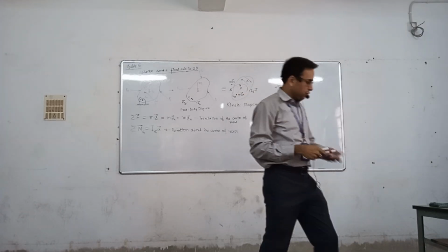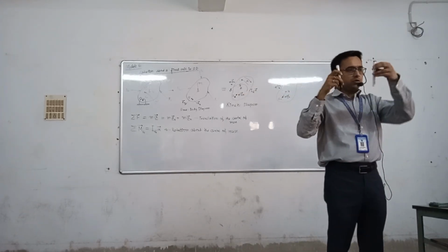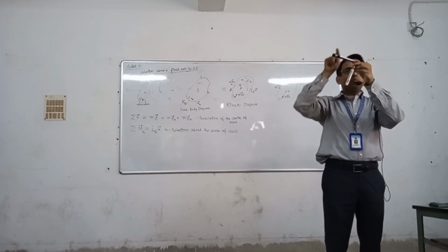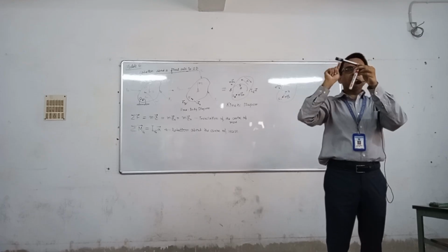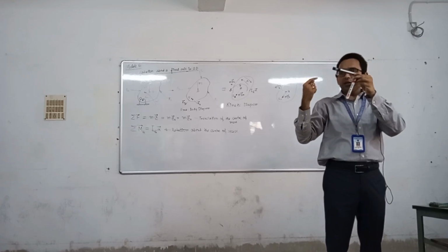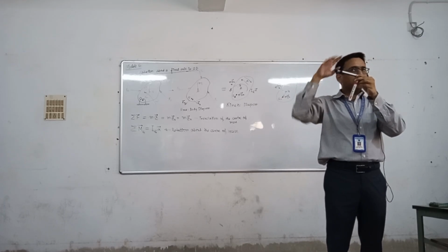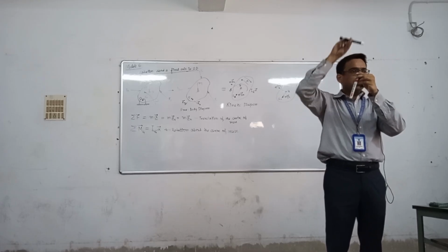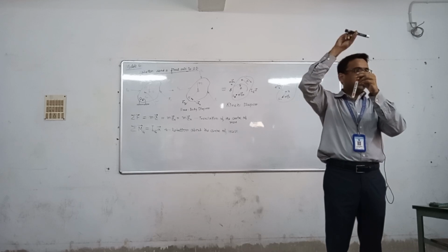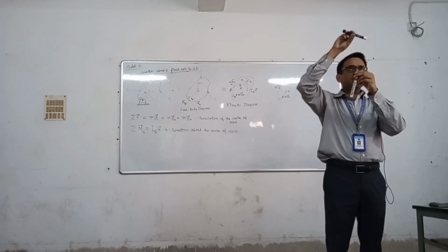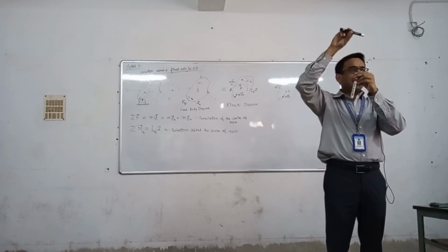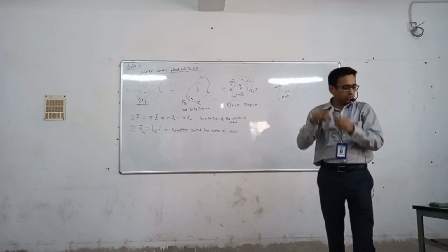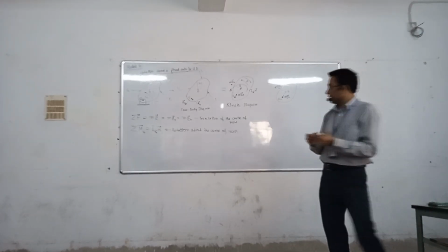Means you have a force in the normal direction and a force in the tangential direction, and another moment is there. Now I know that by an equivalent force couple system, I can combine that moment and this force into a force only, which can be this force shifted at a later point, so that this force at a later point will accommodate that couple or the moment. So that comes from the equivalent force couple system.